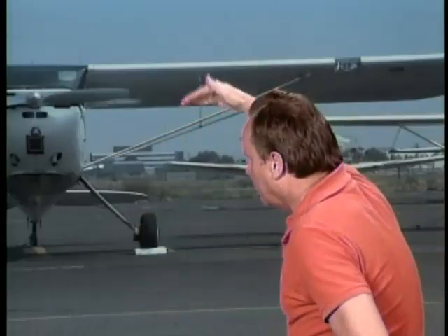All right, now let's assume you wash in the left wing of a monoplane for purposes of rigging corrections. Will that increase drag or decrease drag? Well, it'll increase lift and it'll increase drag. And so washing in increases lift and increases both drag and lift and increases the angle of attack.